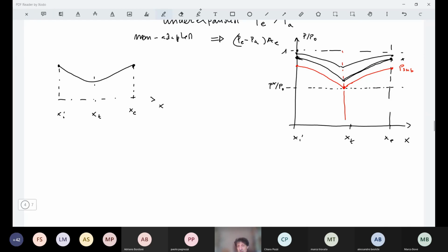We recall what we analyzed with lambda. We can switch to the supersonic branch and reach this other special value of ambient pressure that is referred to as P sup here, the supersonic value, which corresponds to seeing that we continue to decrease pressure now. That means we are increasing velocity, we are increasing Mach number, and we are decreasing pressure.